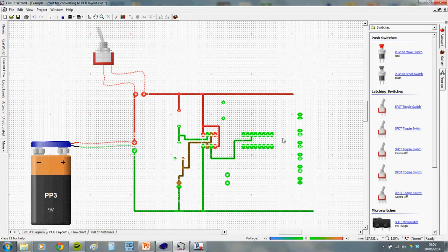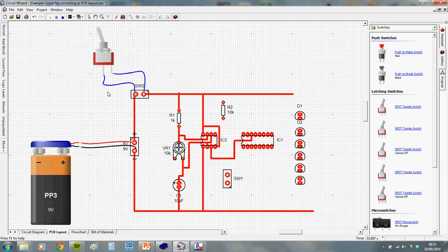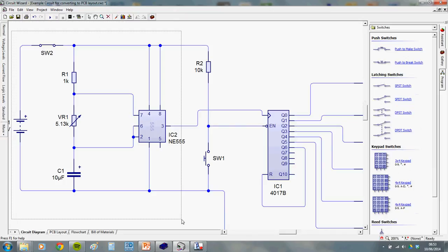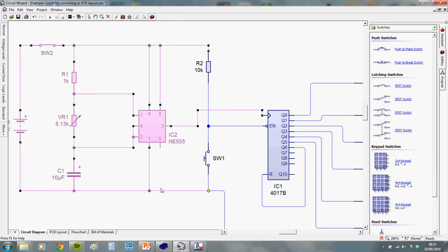All I've got left to do is build the right hand end. Now again, I'm not going to bore you by making you watch me build the right hand part of the circuit. I'm just going to build it and show you it finished, and then talk you through the next stage of what you need to do with your projects. All I'm saying is I recommend as you build bits, if you can test it at different stages, then test it. The timer circuit should be making a pulse. So when you've built the timer bit, as in this bit here, why not see if it's making on and off pulses? Right, I'll be back in what seems like no time at all once I've finished off these other connections.